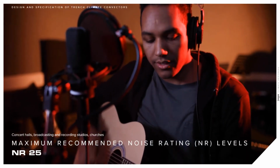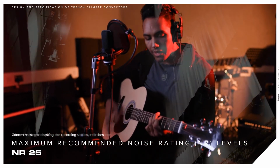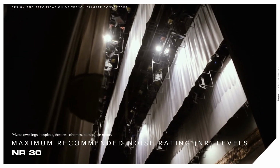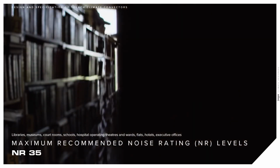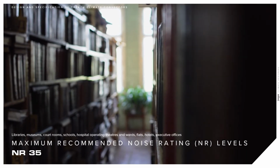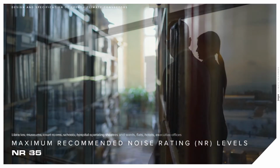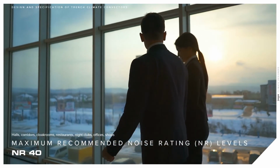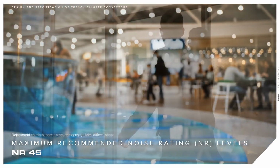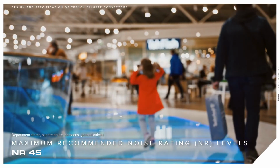NR25 is recommended for concert halls, broadcasting and recording studios, and churches. NR30 for private dwellings, hospitals, theatres, cinemas, and conference rooms. NR35 for libraries, museums, courtrooms, schools, hospital operating theatres and wards, flats, hotels, and executive offices. NR40 for halls, corridors, cloakrooms, restaurants, nightclubs, offices, and shops. NR45 for department stores, supermarkets, canteens, and general offices.